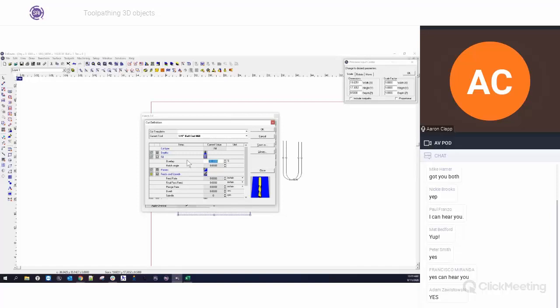So what do we do? Well, we can go up higher. Depending on the material, depending on the hardness of the material, will depend on what you do here. I think the maximum the software will do is 97%. Okay, 97%, that's a little overkill. 95, I guess 95 is what it allows. So that's a little overkill. Most of the time, you can get away with 87 to 90% overlap, and that allows you a very, very smooth surface.